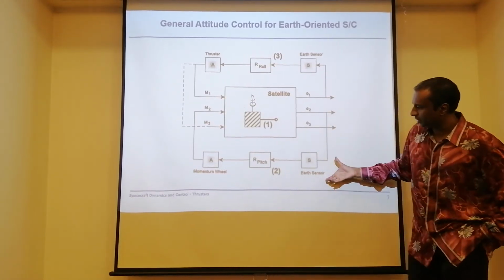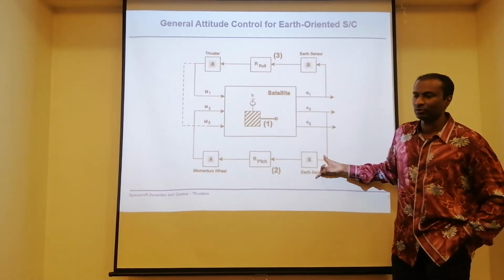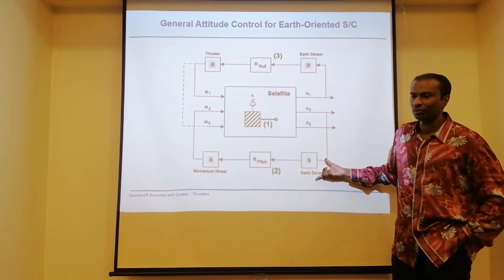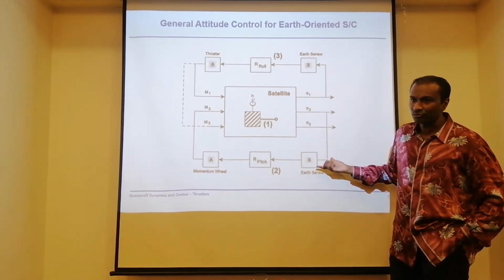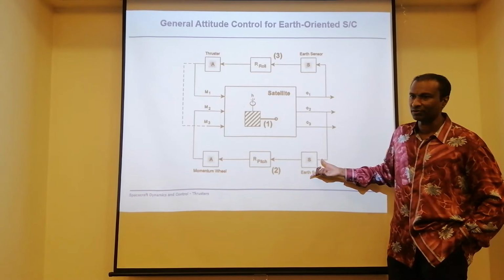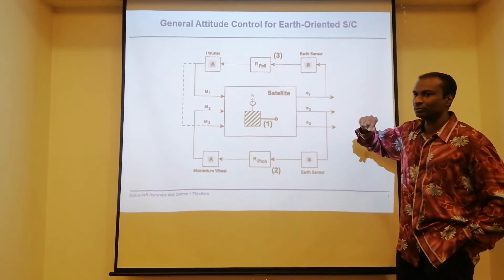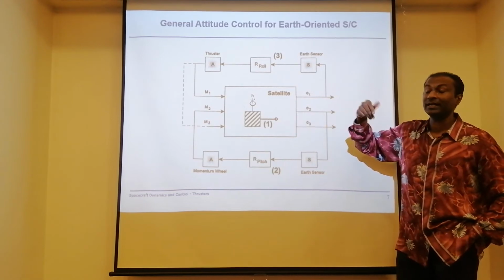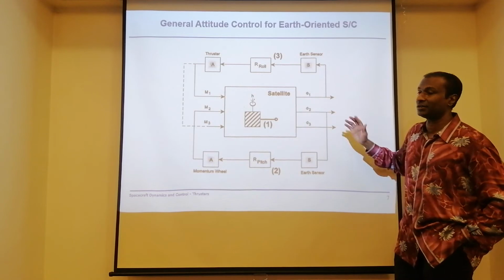See this? This is the pitch sensor measurement. What you want to measure is the attitude. What can you use? You can use a gyro, for sure. You can use the gyro to measure. So I have only two gyros, and I can control 3 axes. That means indirectly, my third axis is the yaw axis, I don't worry.